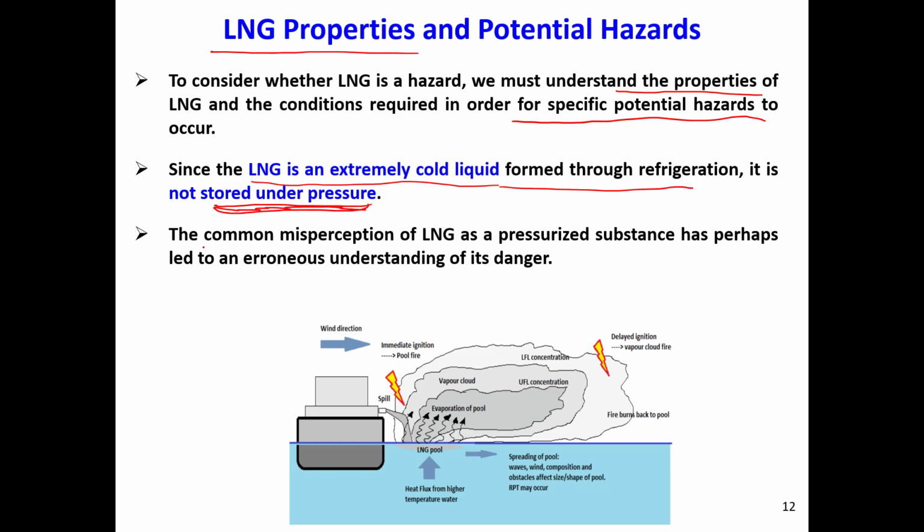This is a common misperception that LNG is a pressurized substance. Yes, under some conditions the tanks can be pressurized if the temperature increases, because gas goes to the vapor phase and can increase the pressure. But in general, in normal conditions, the LNG tanks are not under pressure.